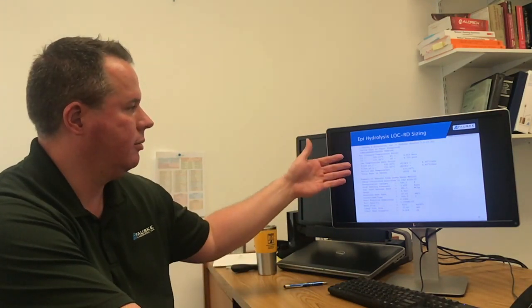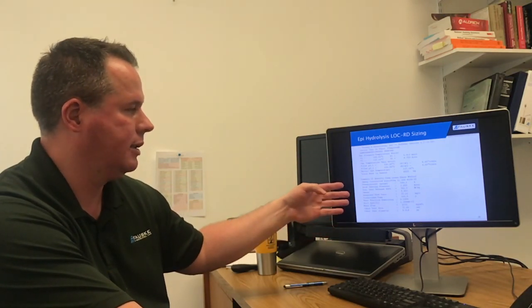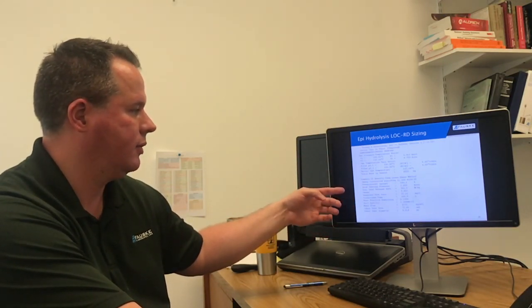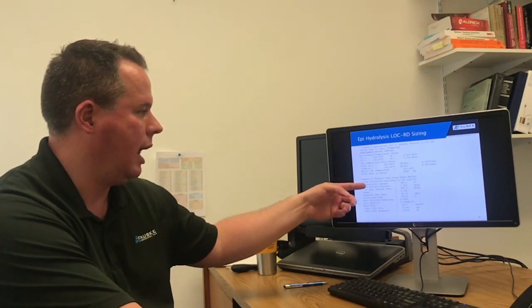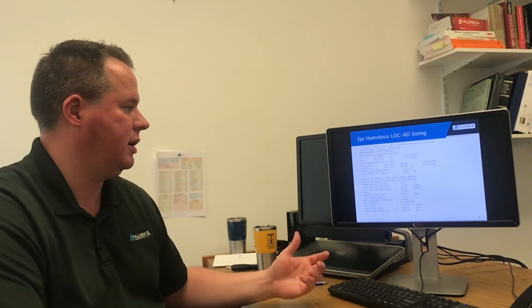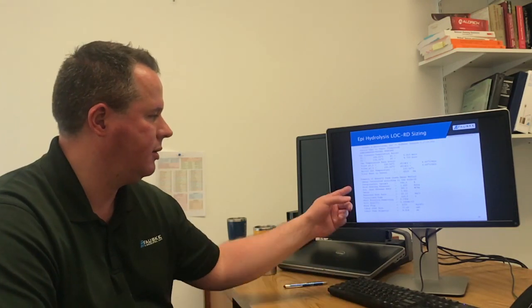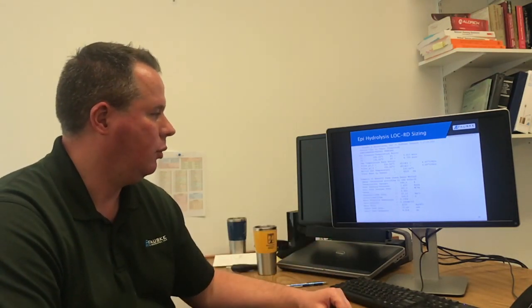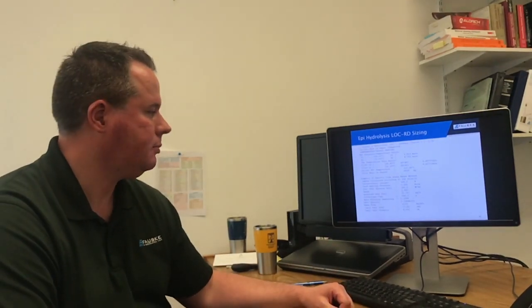So then the Prevent software takes these inputs and goes ahead and calculates the relief size requirement. We have 146% available of overpressure to work with to get to a peak venting pressure of 1.65 bar G, which is 10% over our MAWP.